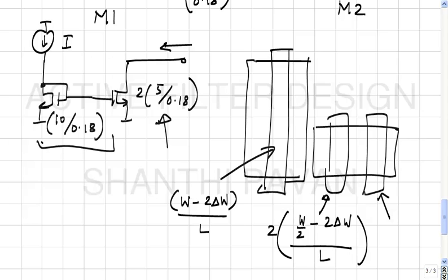And if the parasitic at the source is important, then you will share the sources. If the parasitic at the drain is important, you will share the drains. It's common sense. That's all. Once you know this, depending on the situation of the circuit, you know if the source parasitic is important, or the drain parasitic is important, and choose appropriately.